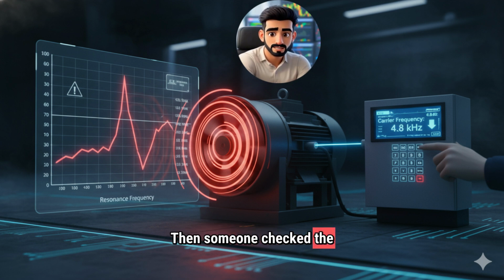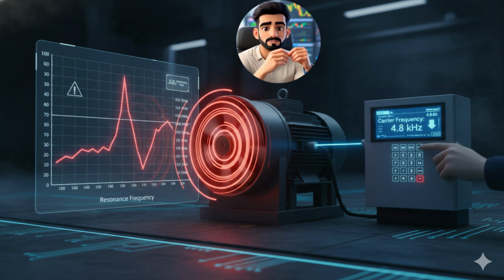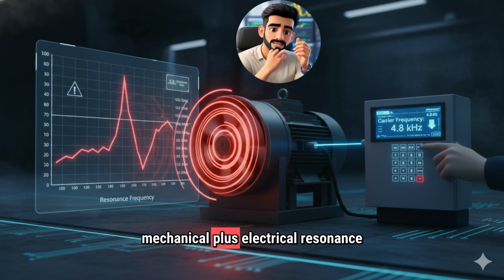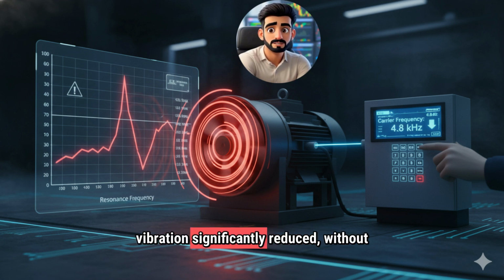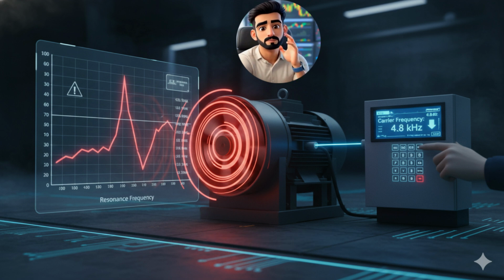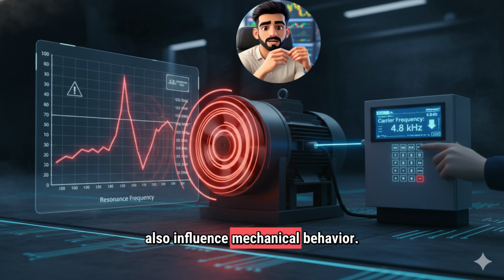Then someone checked the carrier frequency setting. It was found that the carrier frequency on the drive was set to a value close to the mechanical resonance frequency. This caused a combined mechanical plus electrical resonance in the system. When the carrier frequency was slightly adjusted, the vibration significantly reduced without changing any mechanical components. This example shows that VSD parameters not only impact electrical aspects but also influence mechanical behavior.